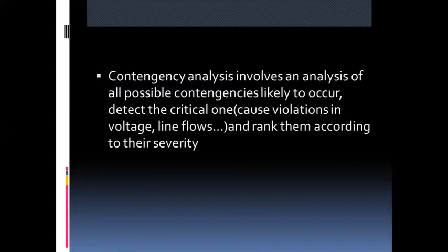As I told you earlier, this is done using a simulation package, because in a large power system we have to simulate the loss of any one generator. If any one generator is out of service, what will be the power flow in the line? What will be the voltage at various buses? All these have to be analyzed.